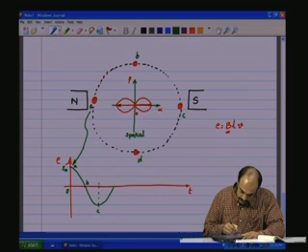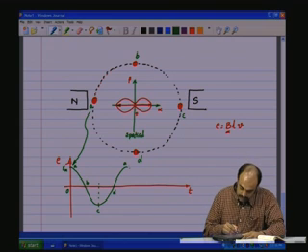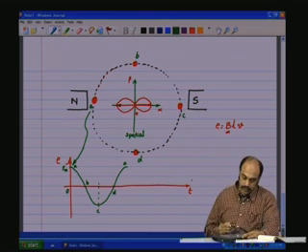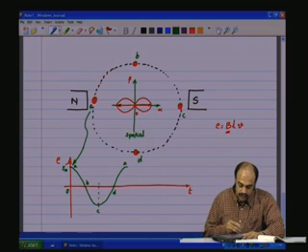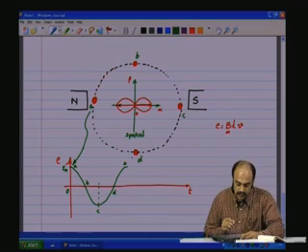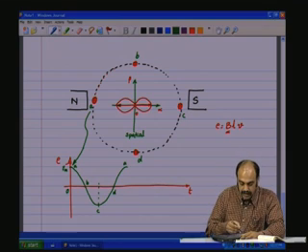And then from there, this is point D, and then again D to A. This again is point A. So, this keeps going on and on. This is for one complete cycle of rotation. You see that you get an almost sinusoidal voltage that gets induced on the conductor as the conductor is moved from A to B, B to C, C to D, and so on.